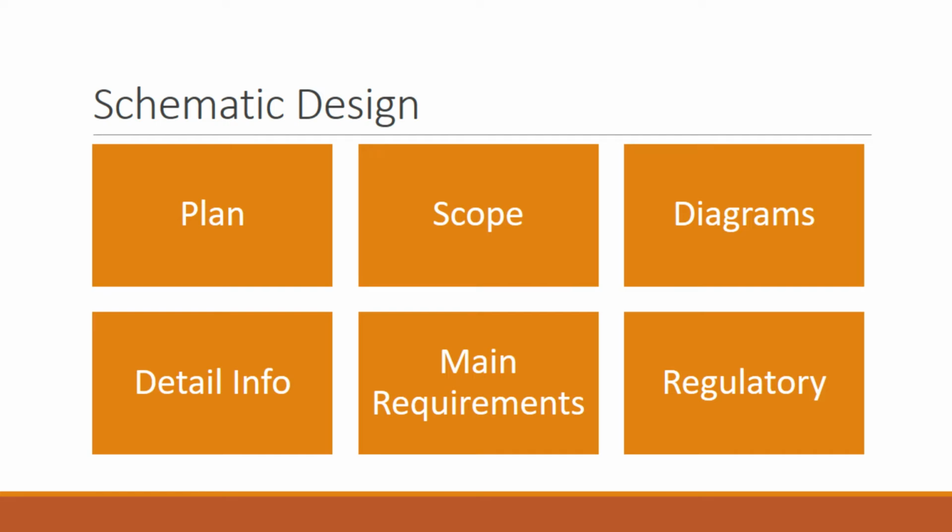Now, following the creation of the deliverables as I just mentioned, the cost estimate can be further refined and revised with an expected error range of now 15 to 30% depending on the complexity of the project. The estimate can now be created using the same resources as the previous stage, with the exception that assembly estimate approaches can also be used along with a smaller amount of unit takeoff and vendor pricing data.